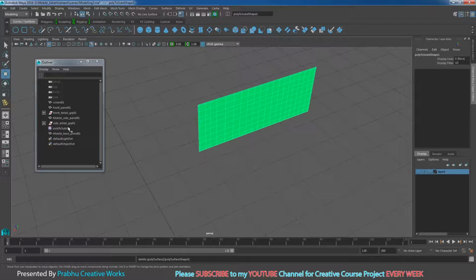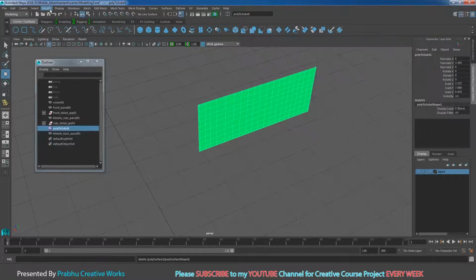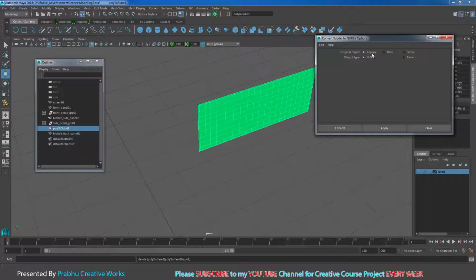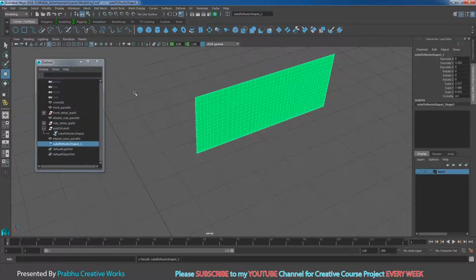So now select the poly to sub D, go to modify, convert and choose the sub D to NURBS option box. Here you need to choose replace and NURBS and choose convert. So it will be converted. So expand this group. So expand this one. So select this sub D to NURBS shape. Press shift P on the keyboard. So when your object is selected, go to edit, delete by type and choose history.